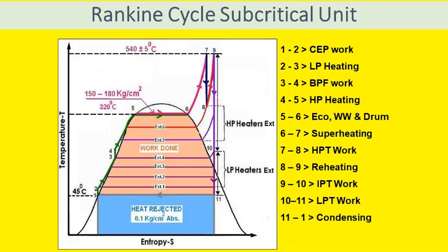In fact, if you see the total cycle work output, the maximum work output is coming from the LP turbine, and 11 to 1 represents the process of heat rejection in the condenser.